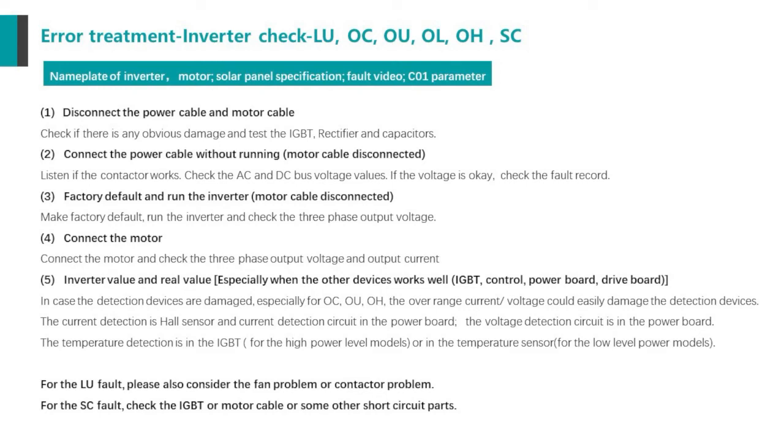There are also some seldom reasons besides those just introduced. For the LU fault, you could also consider the cooling fan problem or contact problem. For the SC fault, here I want to emphasize it again. Please check and test the IGBT at first, in case the IGBT is damaged and you run directly and fire burns the VFD directly.